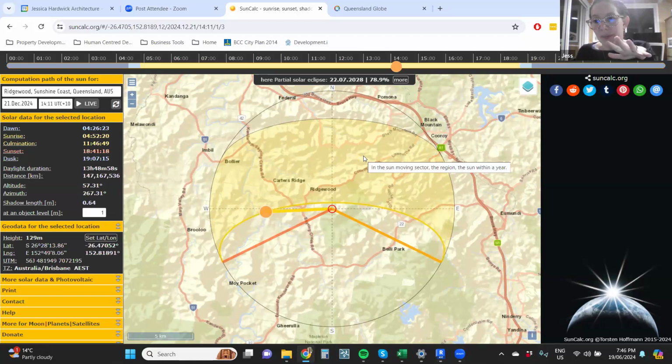And in terms of just a basic exercise, being able to find a great aerial photo of your site and then print off your winter and summer sun paths and then pop them onto your site orientated correctly, because obviously where your site sits relative to north won't necessarily be straightforward, is really, really helpful for you to be able to see where the best path forward is, even for renos. So yeah, that's a really useful tool that I would highly recommend.